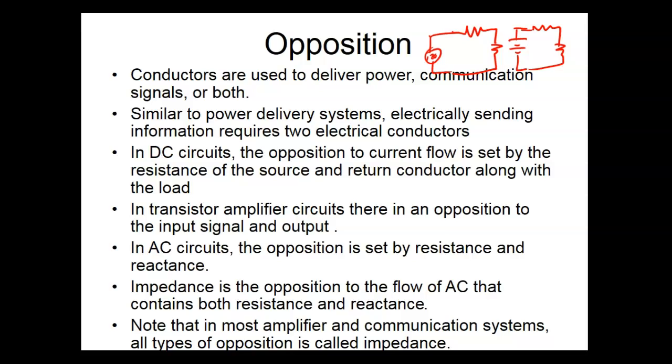Well, the problem is in headphones, when they say it's an 8 ohm speaker, if you put an ohm meter across it, it's going to measure maybe 5 ohms, because that is not a resistance, that's an impedance. Impedance for speakers is set at 1,000 hertz. So if you put 1,000 hertz on a speaker and measure your current and your voltage, it would give you 8 ohms. So that's an impedance, right?